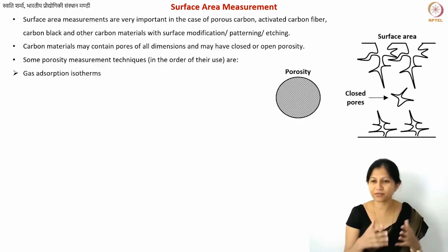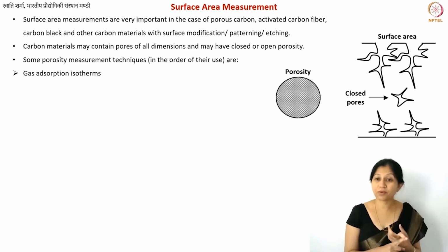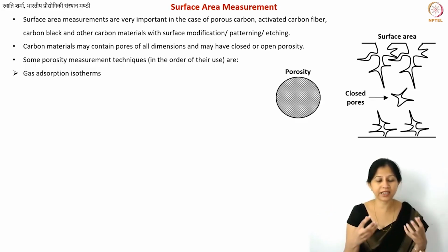So this is the relative pressure that you are measuring. Okay, why do we choose inert gases? Because we want to make sure that the adsorption is just physical and not chemical. So the gas itself should not react, because if there is any attractive force when it comes to whatever your porous carbons or any other materials, also not just carbons, will also have some surface properties, and you do not want your gas itself to start reacting with the surface properties.